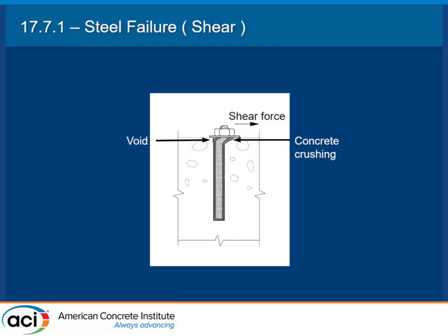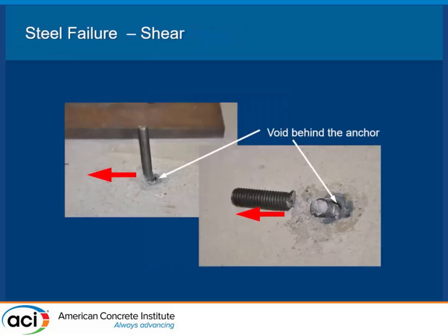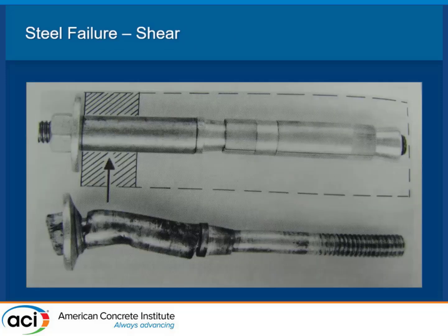The equation you have to do is just the one for steel. I'm just showing you different types of steel failures that you could see in the field. If you're inspecting and it didn't shear on you, but that anchor is deforming to this degree, it is considered a failure.